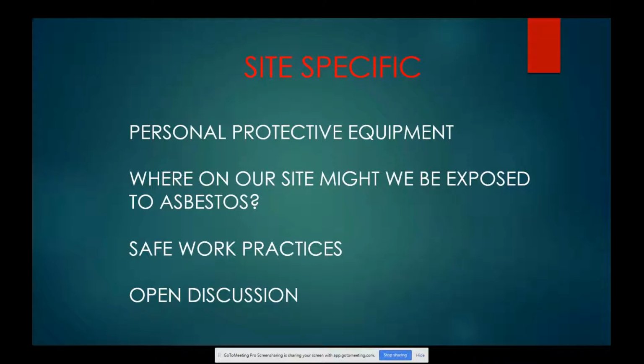and your eye protection. For the most part, with Pickens County, we have non-friable asbestos that comes in that must be double bagged, wetted, and have the official paperwork. It has to be approved by the solid waste manager, and we need time to prepare because we have to cover it with 18 inches of trash over that asbestos.